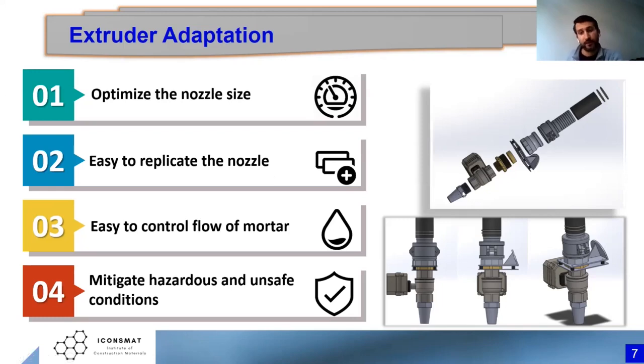If something gets damaged, we can change it anytime. And we have also been using a ball valve. This ball valve is so good to use, because you can control it anytime. If the concrete spills, or sometimes the concrete flows more than enough, you can control it with this ball valve, and it connects to the hose.